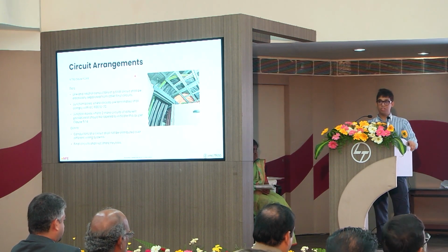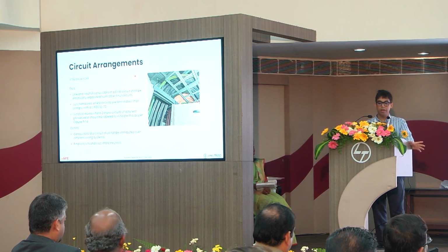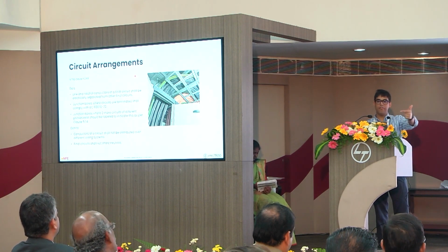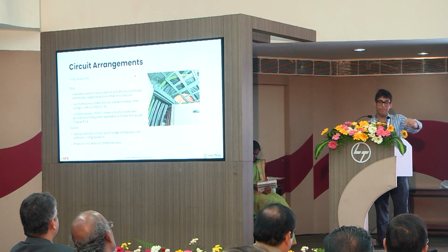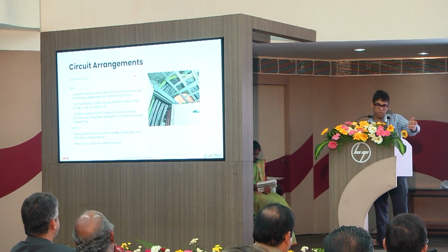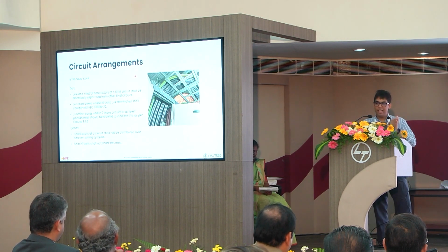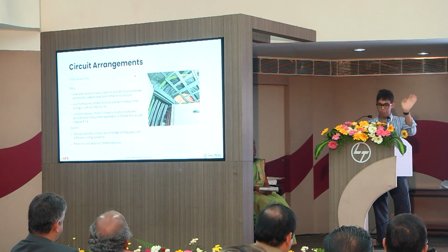And very important, this was something that was shared in the NFE group, a final circuit shall not share neutrals, okay? You cannot have one socket and then one lighting circuit, and then one washing machine circuit, all of them sharing one neutral. In fact, you cannot even have a socket and a light circuit sharing one neutral. Line and neutral for each circuit have to be separate, and in most situations, even the earth conductor has to be run separately from a single point of earthing.